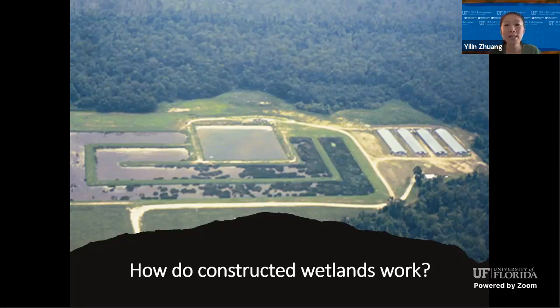This cell is planted with wetland plants such as cattails; roots and stems of the plants form a dense mat. In that cell, chemical, biological, and physical processes occur to treat wastewater. Water levels are controlled in both surface and subsurface systems. In a subsurface system, the normal water level is kept 1 inch below the gravel surface, which improves the treatment and controls mosquitoes. A second or third cell may be added for more treatment.